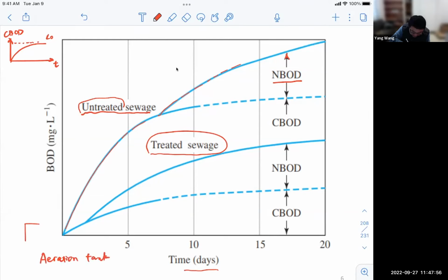So what happened is that in that tank there, for our inflow of the wastewater, we have the outflow. At the same time, we raise those bacteria inside and we provide the oxygen or air inside. This is called the aeration tank. So basically the bacteria that we put into this tank cannot consume the nitrogenous species. So we don't have those bacteria in these aeration tanks.